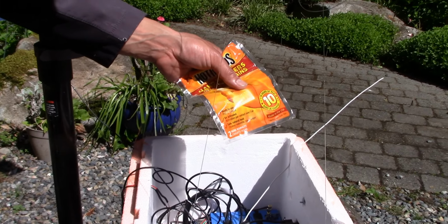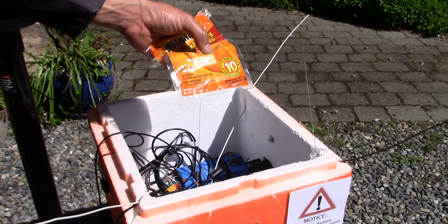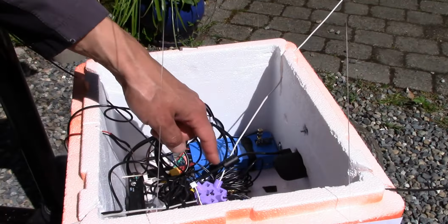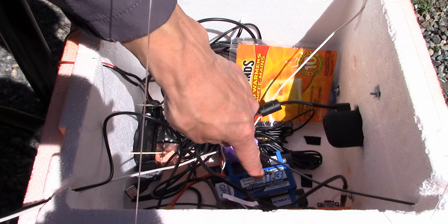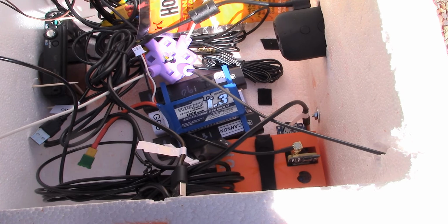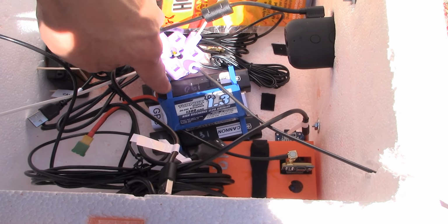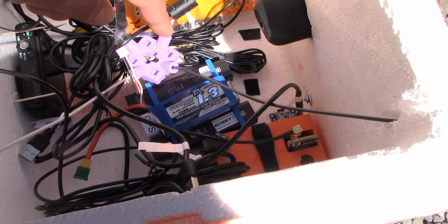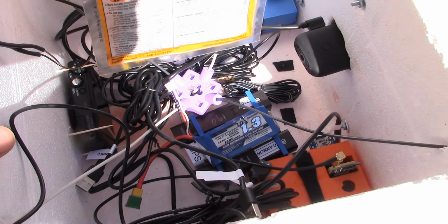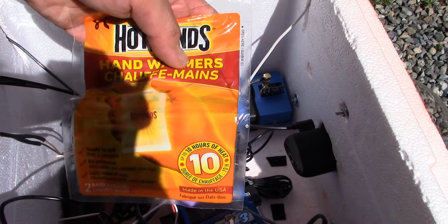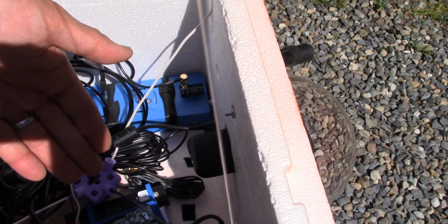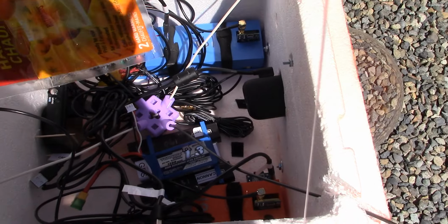These are pretty darn light chemical-based systems that are just going to radiate heat for hopefully the duration of the mission. If you come in here and look, one of the main critical components that we're trying to keep warm are these batteries here. And as you know, lithium polymer batteries do not do well in the cold. So we built a battery stand. I don't know if you can see these. There's this blue 3D printed layout configuration. This holds the batteries up a little bit, and there's room underneath for us to slip one of these hand warmers underneath. So hopefully this hand warmer is going to warm up, and the heat is going to radiate up through the batteries and warm up the entire system, the entire interior of the payload box.